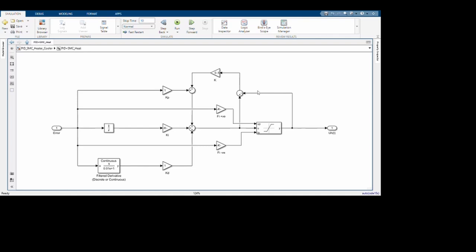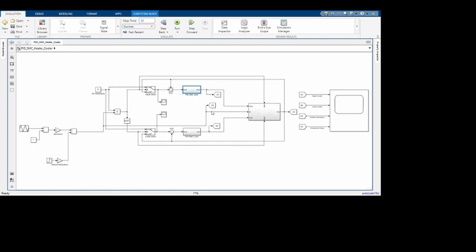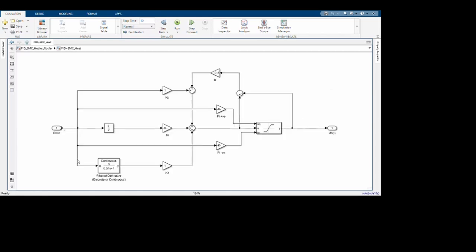We have implemented our PID controller by simply having an error block which takes our set temperature and subtracts our output temperature. So that's giving us a feedback loop. When that gives us a feedback loop, an error is generated. That error goes through a proportional gain of 1. Now, the way I calculated these gains is by simply taking our first order equations. Yes, our heating and cooling models are first order equations, and substituting our PID output u of t in them.